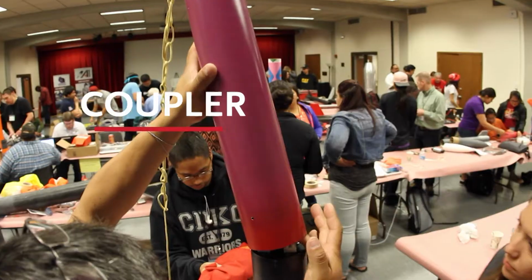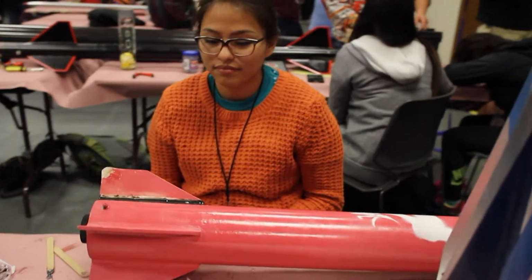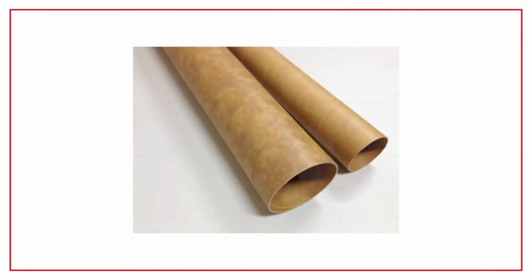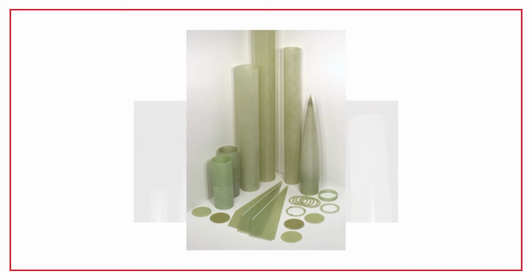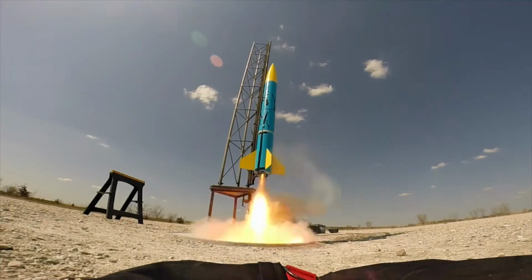While many rockets flying H-class motors may be made of laminated cardboard for budgetary reasons, you should consider phenolic tubing, polymer plastics, fiberglass, and carbon fiber materials when flying a high-powered rocket with an I-class motor or above.